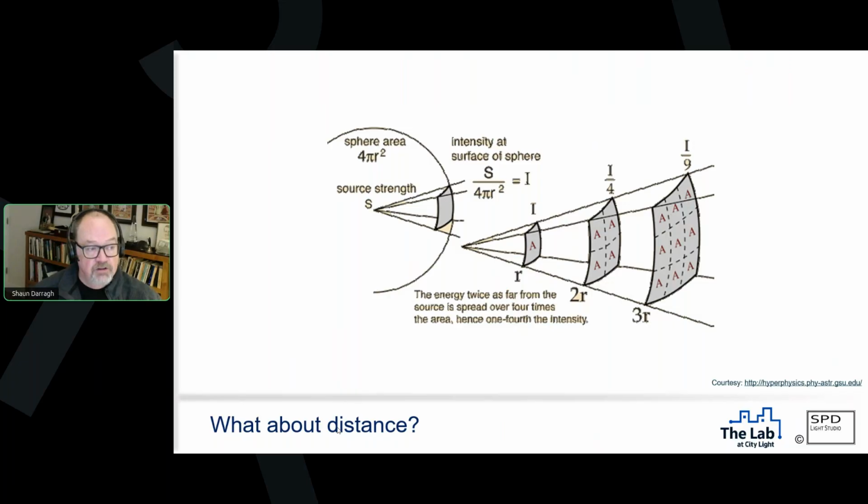So if I have a task light here, and I want something to be brighter, I bring the task light closer to it, right? I can use my general lighting in my office to get to those higher light levels if I want to, but it's much less efficient. It's more efficient for me to bring the source closer, right, when I can. I hope that makes sense to everybody.